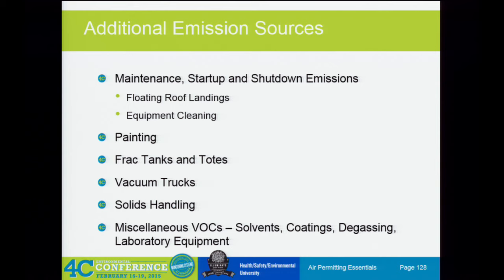And that's preferred because there's PM deviation, right? There's PM, PM10, PM2.5, and a bag house has a different efficiency for each one. So if you have different sizes of PM going into the bag house, you don't have the same collection efficiency across all species of PM. So the method that you brought up is the preferred method of calculation.